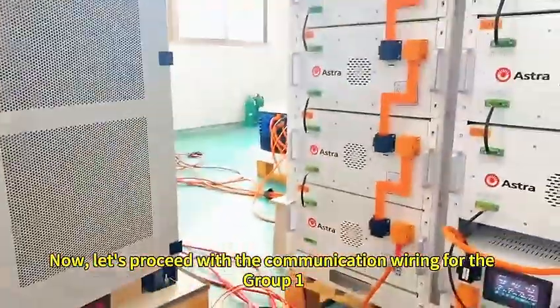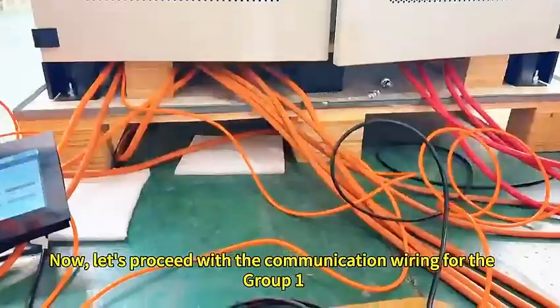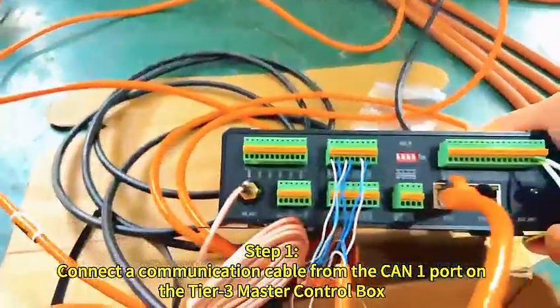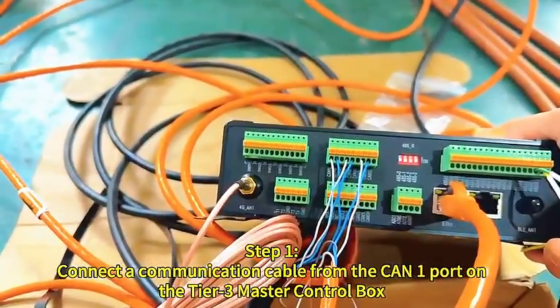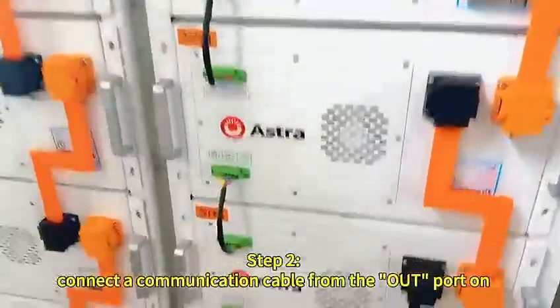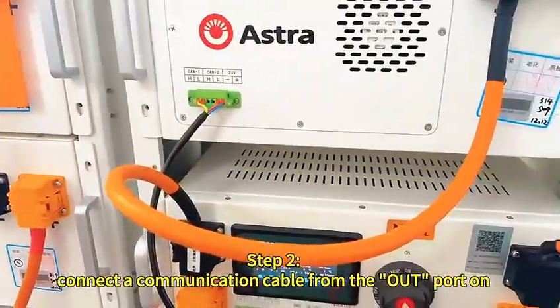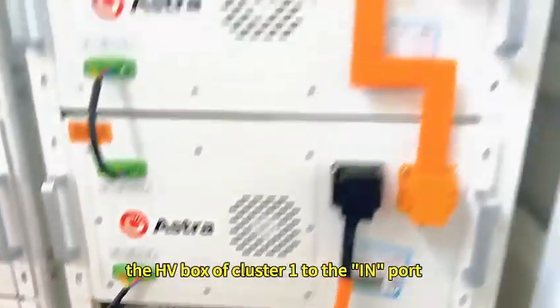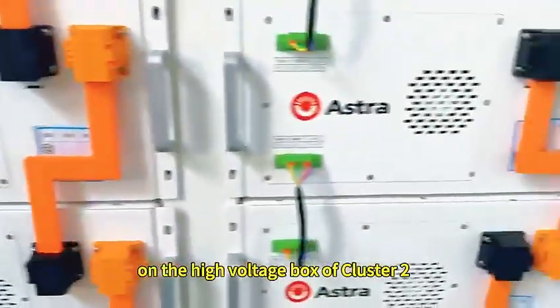Now let's proceed with the communication wiring for the Group 1. Step 1. Connect a communication cable from the CAN 1 port on the Tier 3 master control box to the inverter port on the high voltage box of battery cluster 1. Step 2. Connect a communication cable from the out port on the high voltage box of cluster 1 to the in port on the high voltage box of cluster 2.